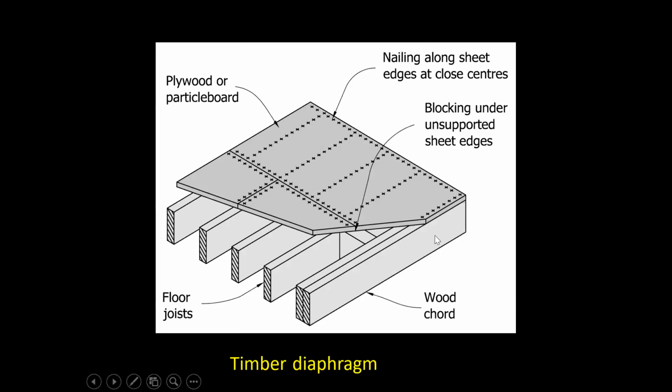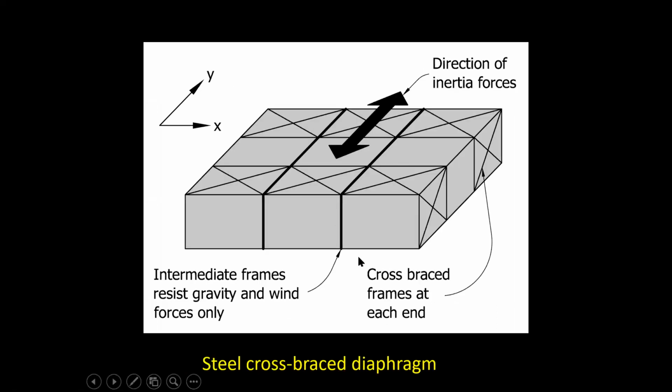In a wooden building, where you've got wooden floors, the diaphragm would be usually made of plywood, and it can be a very good, strong diaphragm. Here, your timber or wooden floor joists. But for a wide span structure, this is the sort of diaphragm we usually use.